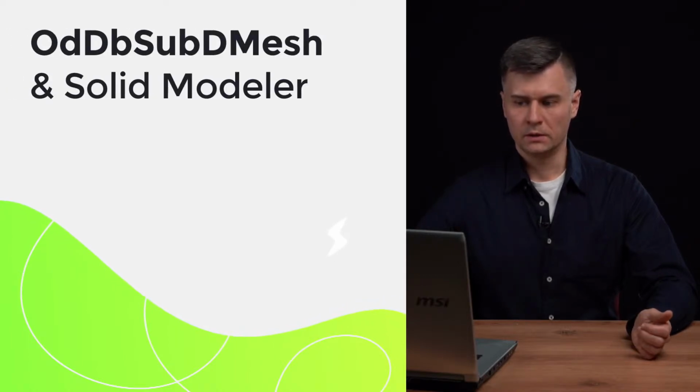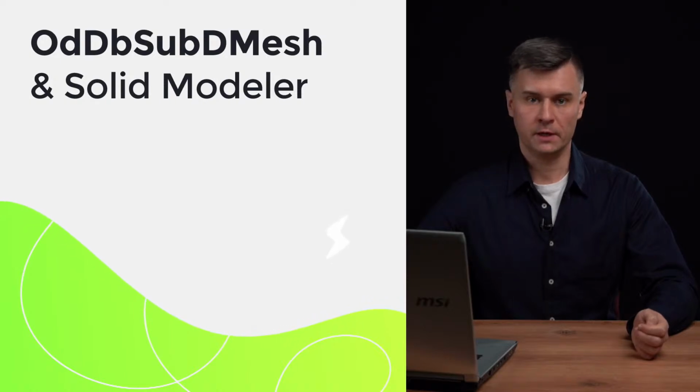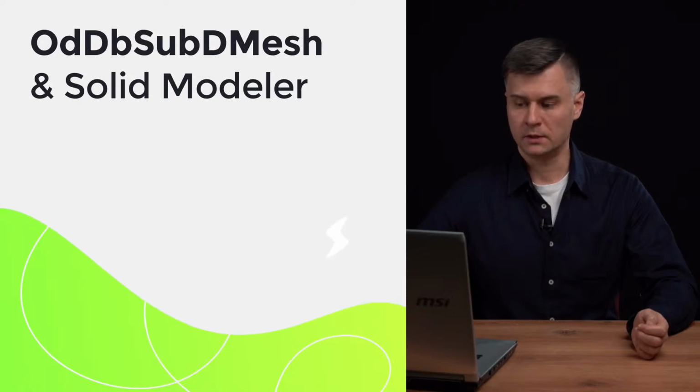Okay, there is one more popular feature in the Drawings product related to ODB submesh and 3D modeling operations. ODB submesh can be created from an STL file by the STLIN command, or by conversion from 3D entities by ODB getObjectMesh to get tessellation and convert to mesh.